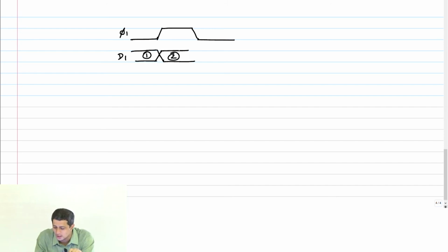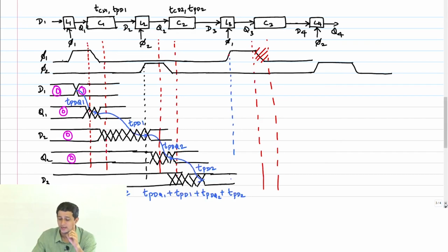Whether the data changes here or here, it doesn't matter. The latch has to hold the data for the remaining part, and if that data is held correctly, there is no problem. That's why I said even before I started, mark your violation windows correctly. Then you will not get confused. If there's no violation window, then there's no issue. Data can change at any point. You may ask whether it is TCQ or TDQ. That may be the only difference.